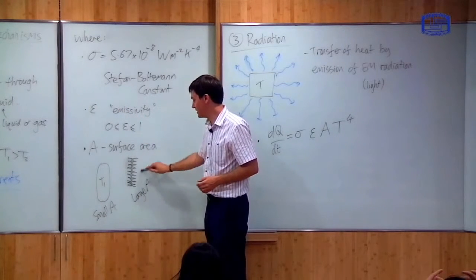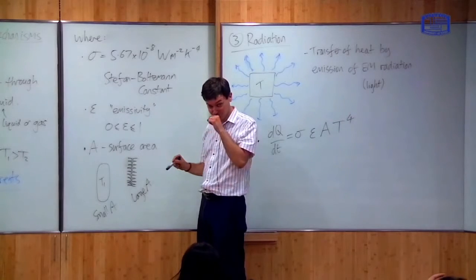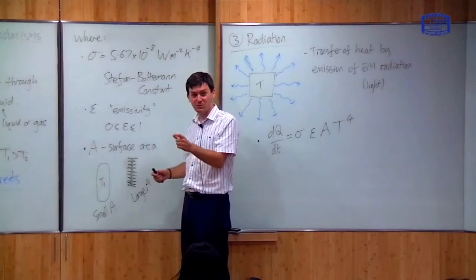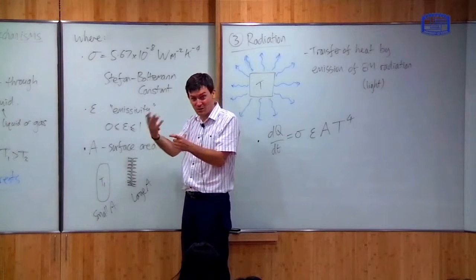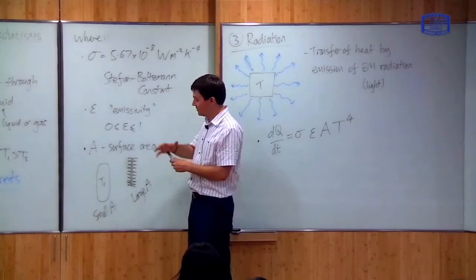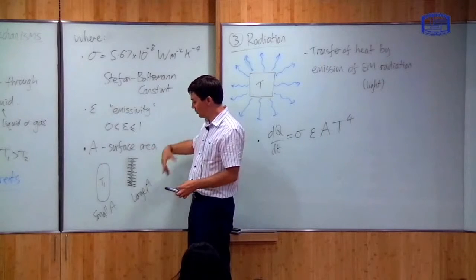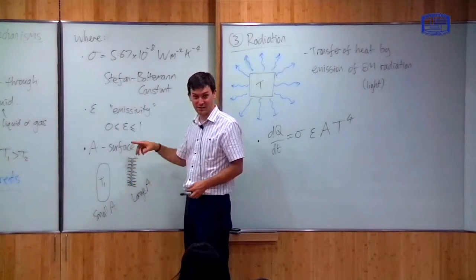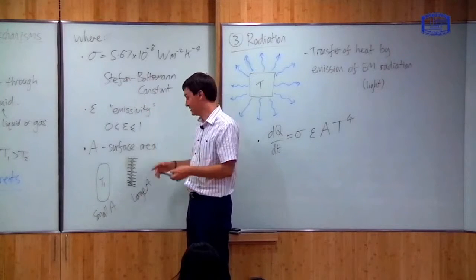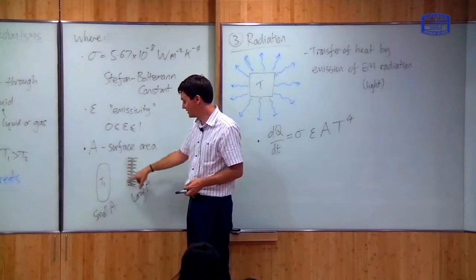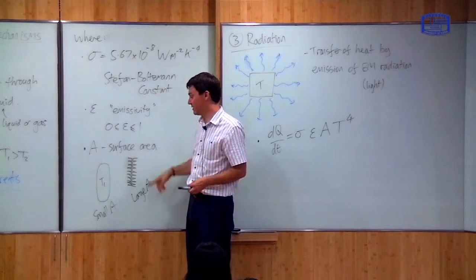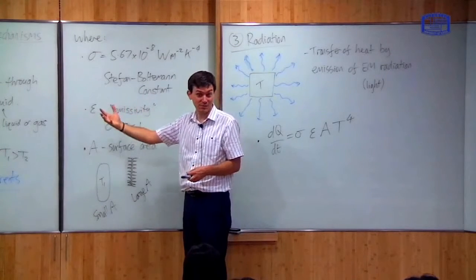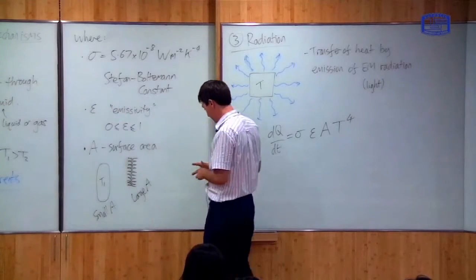Another example of this is, if you look inside a computer, the chip, the CPU, gets very hot, because it's doing a lot of computation. And often, if it gets too hot, it will stop working. So on top of the CPU, you put something which looks like this. This is also called a radiator. And the reason you put something like this is it has large surface area, and therefore it maximizes the rate of heat transfer away from the CPU. That's that.